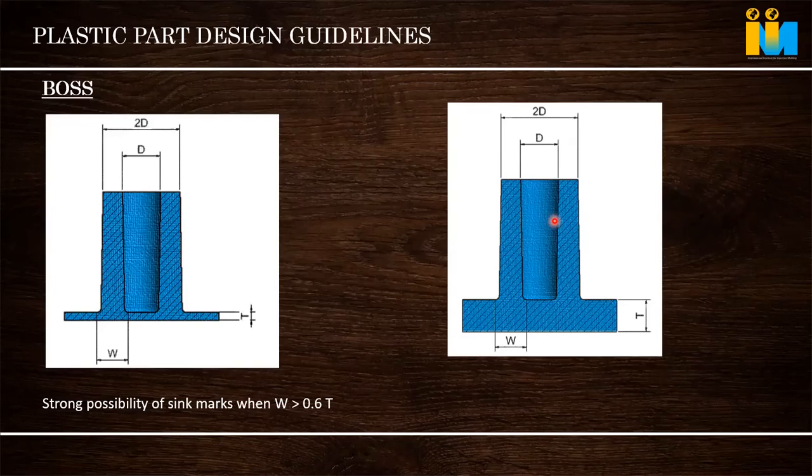Amorphous cannot expand. PP, nylon, PBT, all these materials, if you put a thread, it expands. It will never crack, because its structure is like a bundle, remember, it's a bundle. It has space to expand.